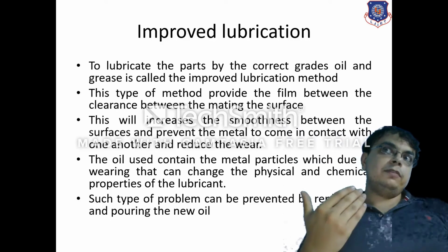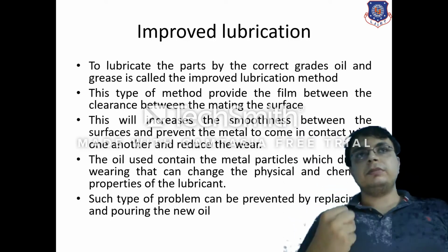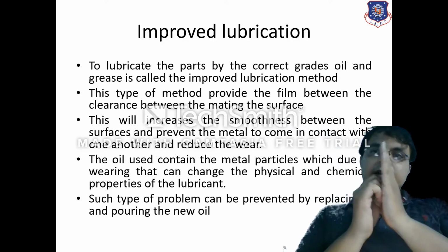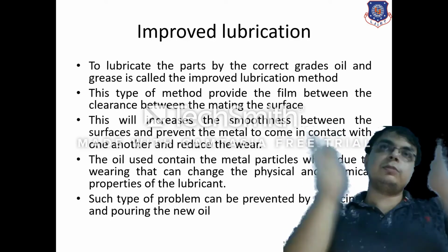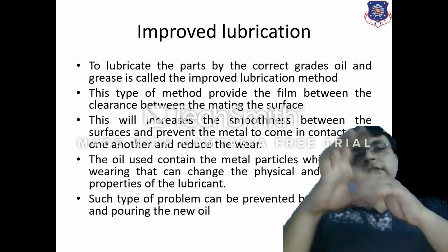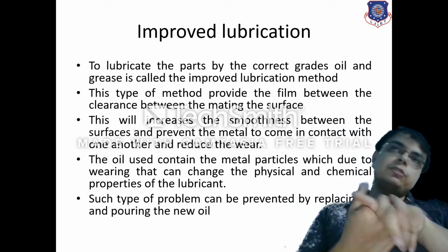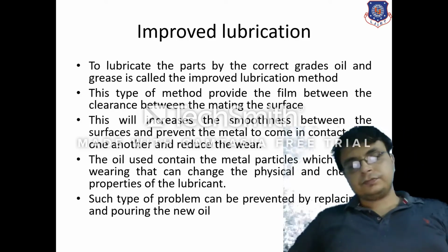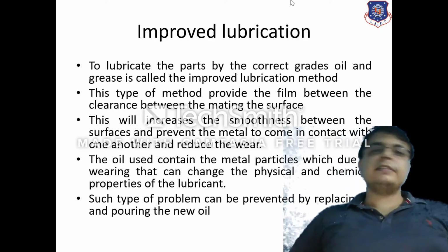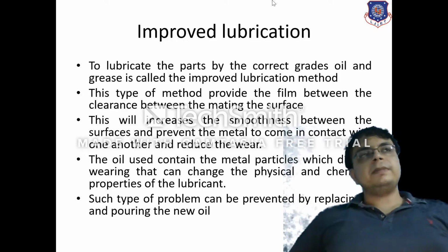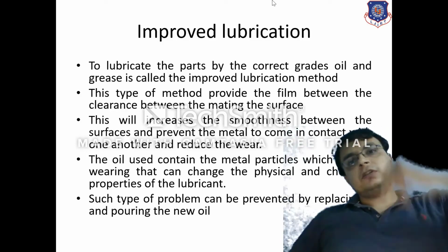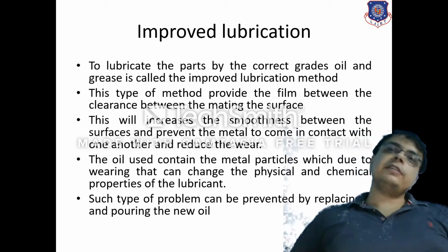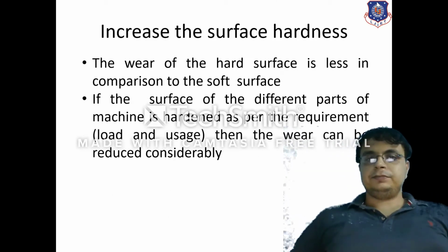Such an oil film is also harmful to the machine because it will again cause collision, because between the two surfaces there are small particles which are in contact with both surfaces. When the particle is between both surfaces, it will cause abrasion. The surface will get rough and the wear will be more. So the only thing required is to replace the old oil with new oil, and as a result the particles present in the oil will get replaced.